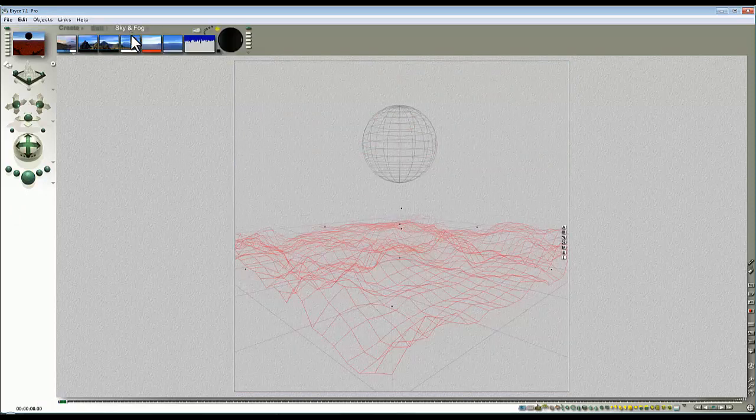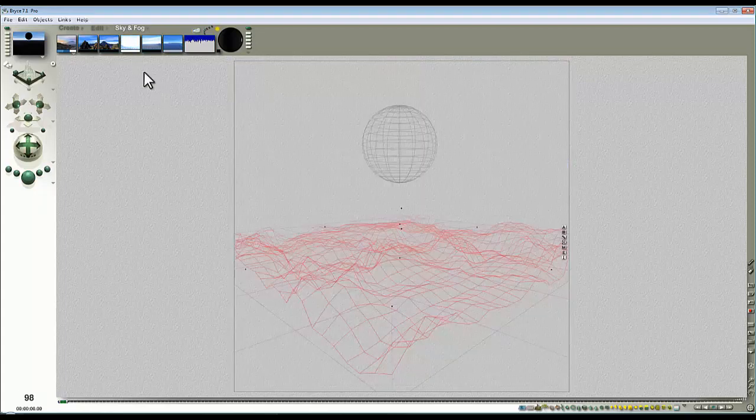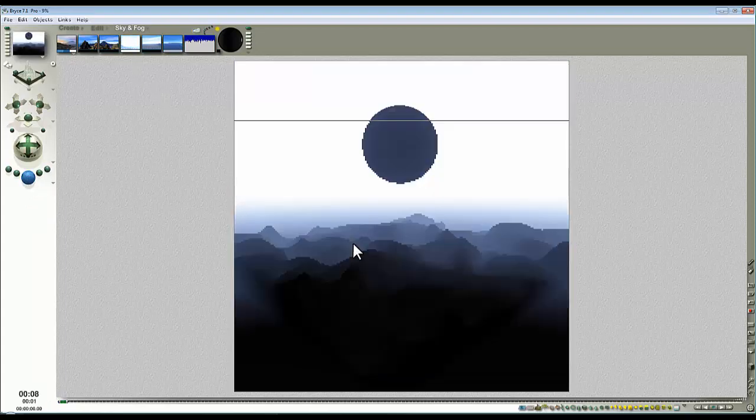So what you can do now, if we've got more sophisticated lighting methods, is also get rid of Skydome colour. So that removes that influence from the scene. So the only thing you can see now, maybe a faint edge here, is a result of the haze effect. The haze effect will, through depth, add lightness to your scene according to whatever colour that is.